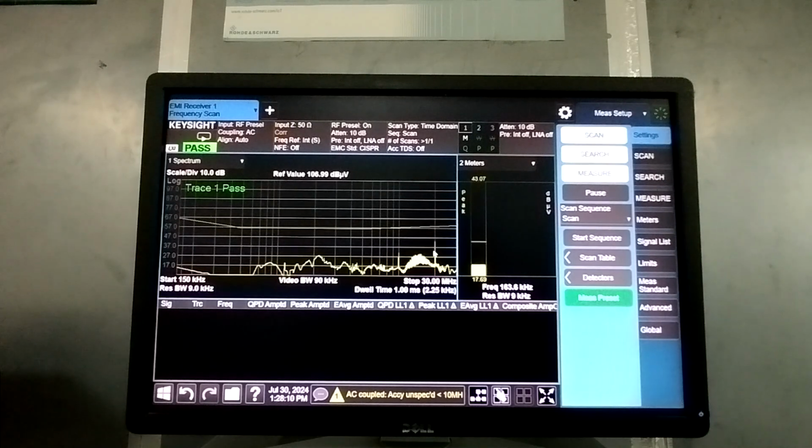Now, this was one of the tests of EMC compliance. For a device to be fully EMC compliant, we also have to check its radiated emission, radiated immunity, conducted immunity, and all other tests, including safety tests, to check whether this device passes EMC, whether this device is EMC compliant or not. Now I will test another device, which is a ViewSonic monitor.